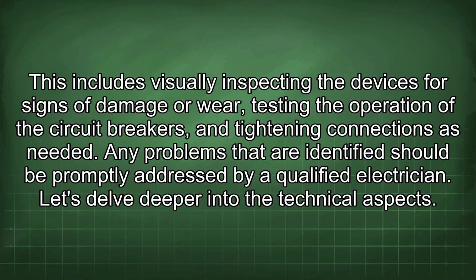This includes visually inspecting the devices for signs of damage or wear, testing the operation of the circuit breakers, and tightening connections as needed. Any problems that are identified should be promptly addressed by a qualified electrician. Let's delve deeper into the technical aspects.